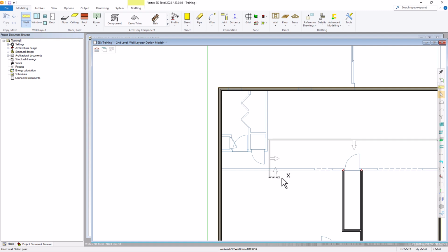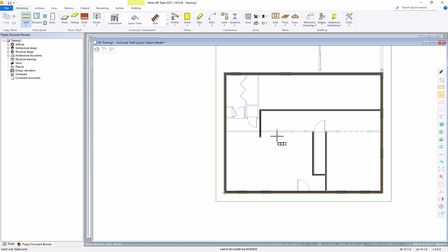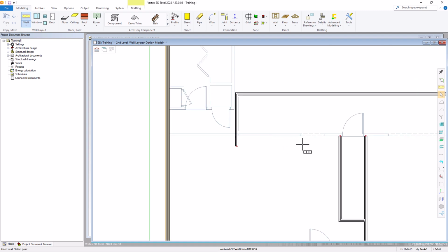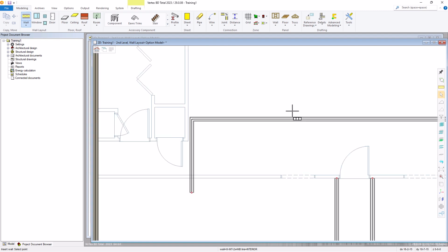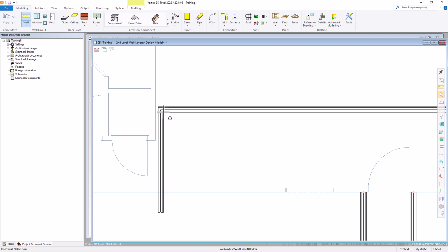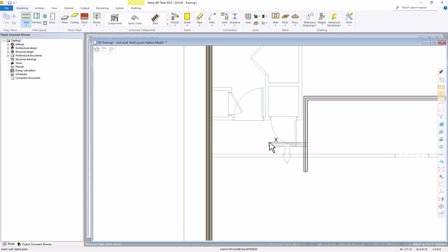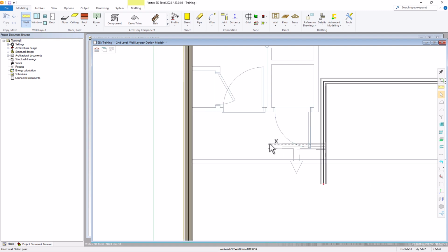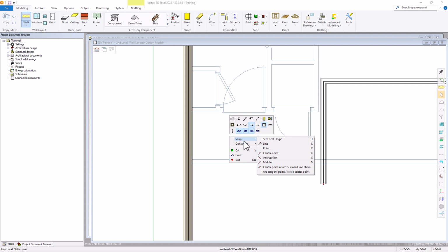Select any point here and then V to confirm. Now we have another horizontal wall that is going to be 4 feet from this wall. So we'll go ahead and Q off this corner. So hit Q, letter I, 4 feet. And we'll run this towards the left exterior wall. And that is offset correctly. So we'll hit the U to lock in horizontal. And yes, it's offset correctly. It offsets downward. And butt that one up. And V to confirm.